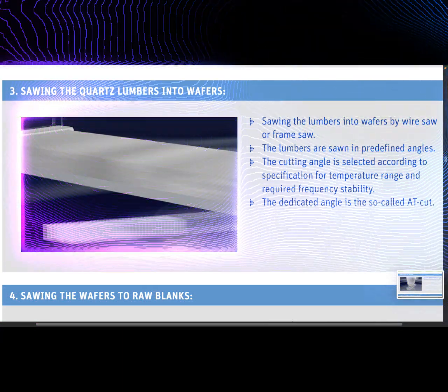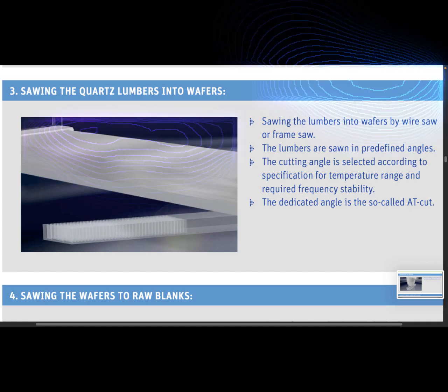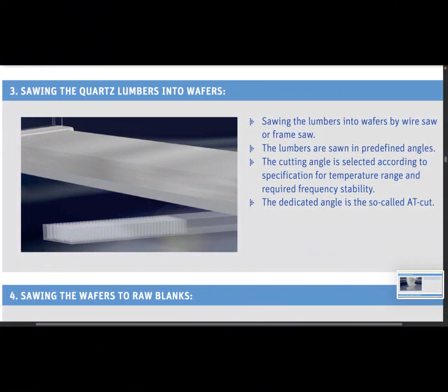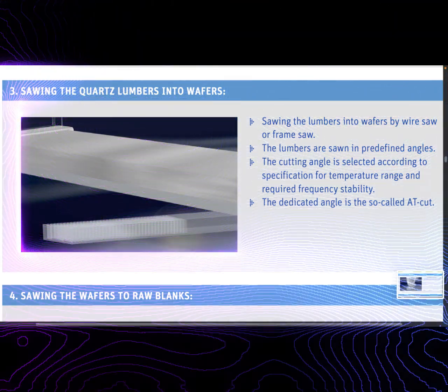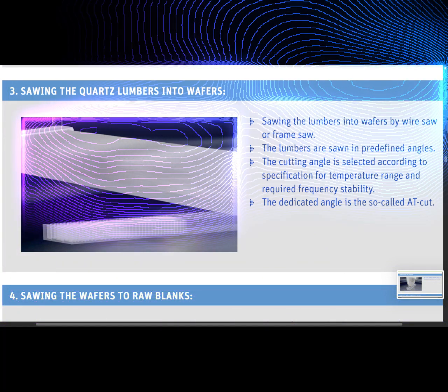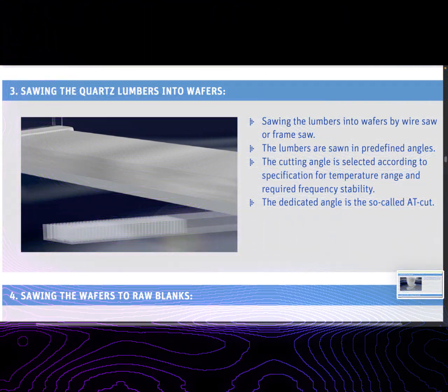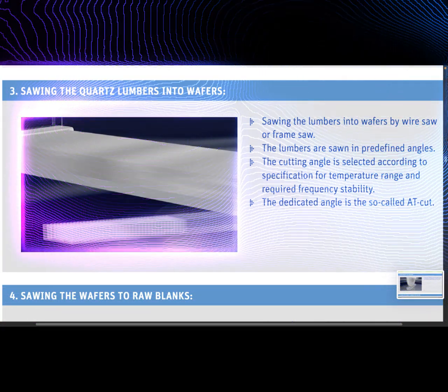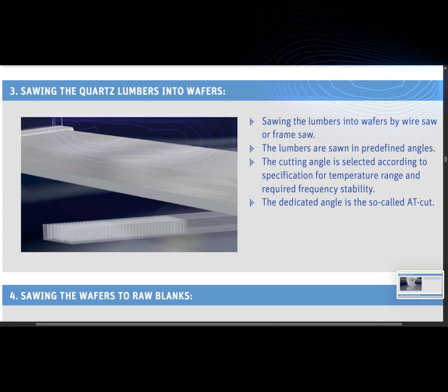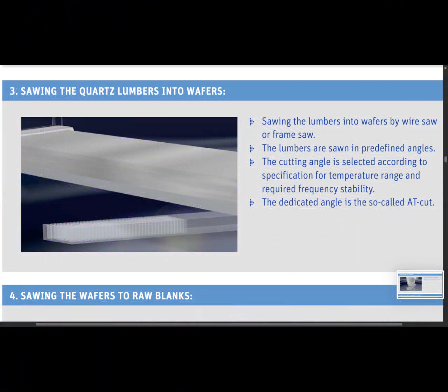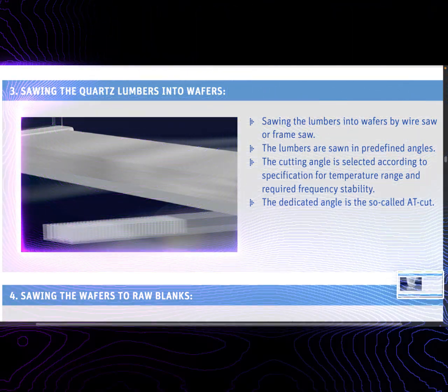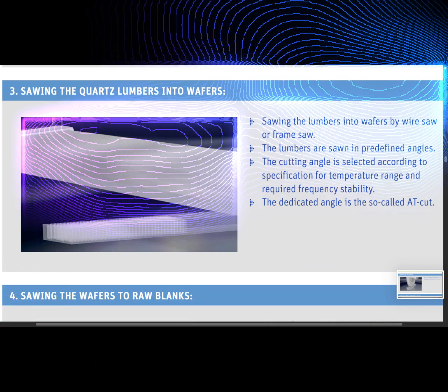Temperature compensated crystal oscillator. Although crystal resonators provide an accurate and stable reference frequency, they are still sensitive to temperature. Some applications need a much more stable reference. For example, GPS requires a stability of about 0.5 ppm or less.